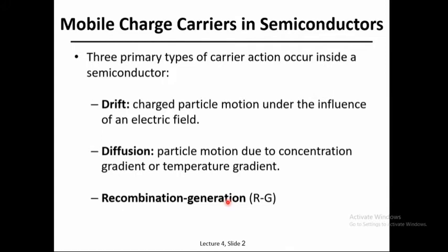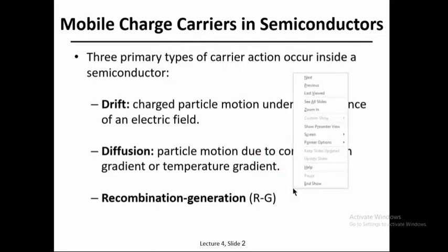So if you recall from last year when we studied the current for a PN diode, or for the bipolar junction transistor, we talked about I being the reverse saturation current times the exponential term of eV over k_B T. While here, what we will be doing is understanding I0, that reverse saturation current, where it came from. We took it as an application as a constant, while here it is the sum of all these currents, the drift plus diffusion plus recombination for each particle.